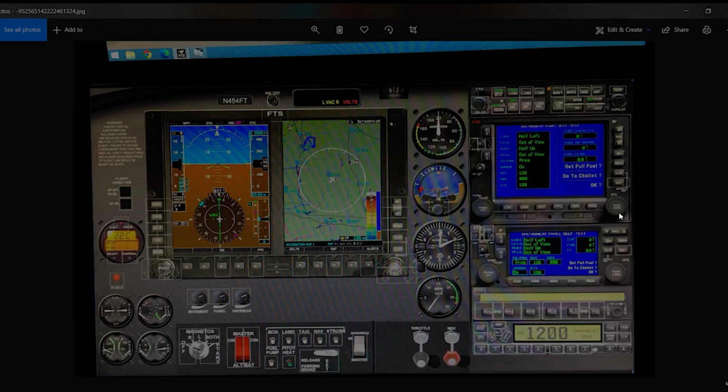And then if you're putting in the flight plan, you'll use push in to open the flight plan editor. Then you use the top part of the rotator to move to each line of the flight plan. And once you're in each line of the flight plan, you then edit by using the bottom side to go through all of your alphabetical and numeric numbers to use to set fixes and airports. Once you have those set, you hit enter. It'll load it into the flight plan.